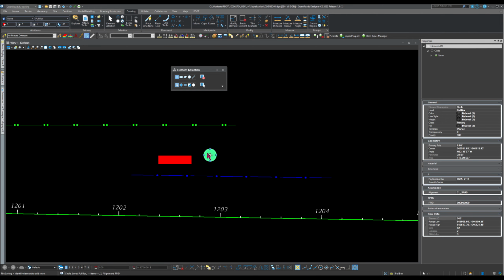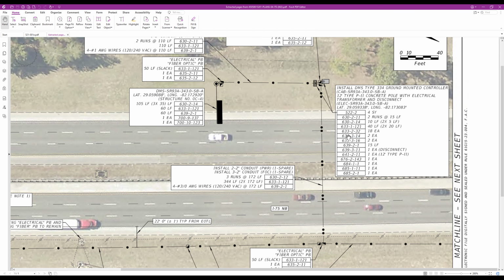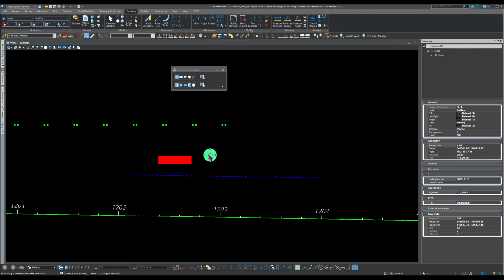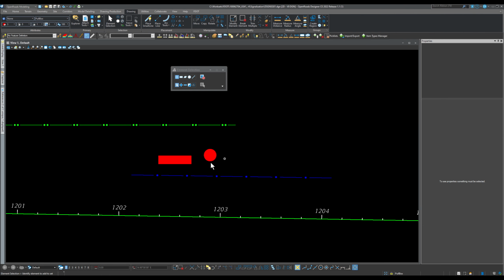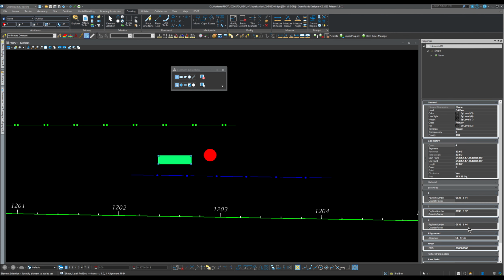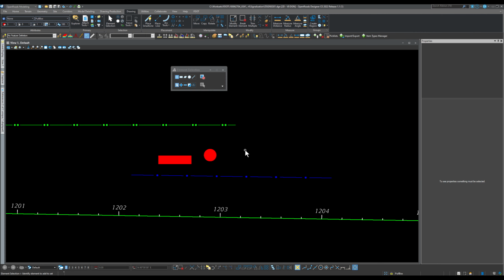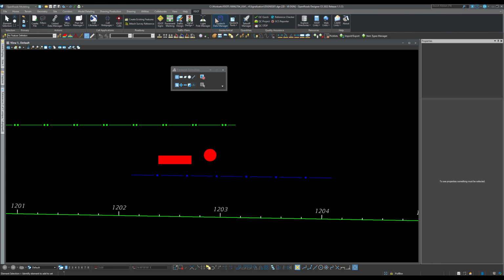And then this pull box. Or you can imagine with me, because this is where it gets complicated, because here some people will have this number and this number, but they want one cell that actually has 2 each. So you can do that. You can have a representation of one pull box, but you don't want it to appear in Excel as 1. I'm actually going to make it appear as 5. And then let's go to these. This one, I want it to be 3. And this one, I want it to be 6. Let's click enter. So now let's run Takeoff Manager and see if that's going to happen or not.